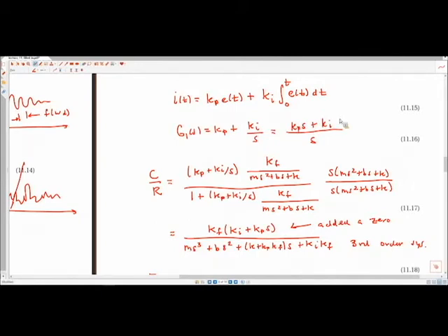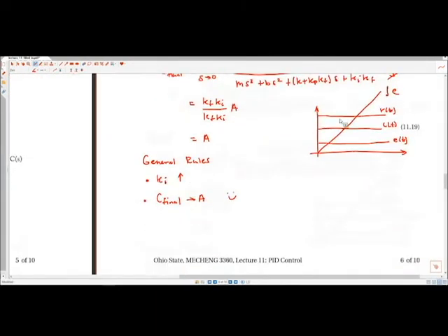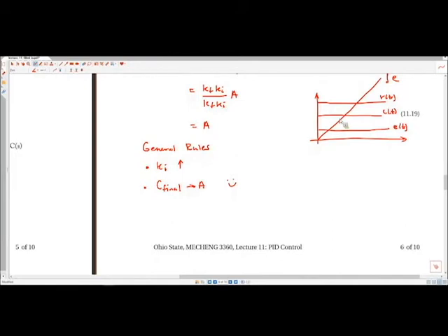And going back to the notes from the Friday before spring break, we saw that as we increase system type, we do better in terms of steady state error. Before, we had a system type 0, with no free integrators in our plant. We now have a combined system that's system type 1. We would expect the steady state error to a step reference to be 0, from what we talked about Friday before spring break. And here's just another way of showing that. So this is the major good effect of why people put integral control in a system.